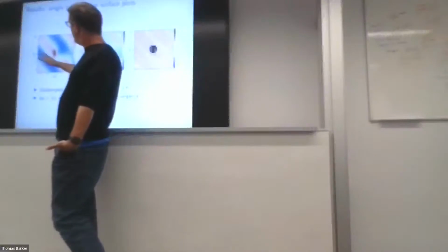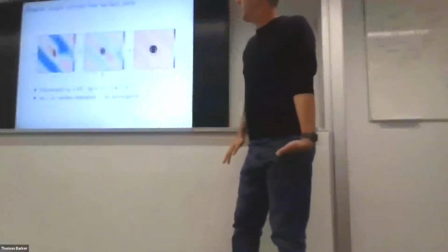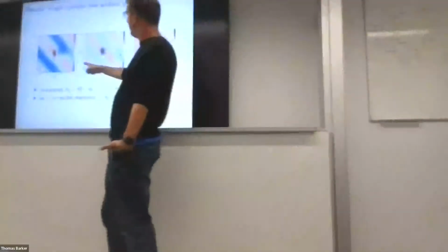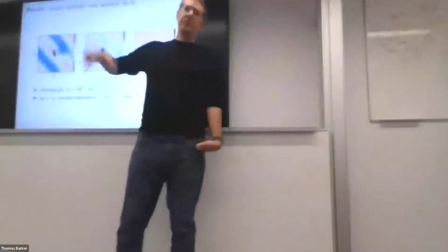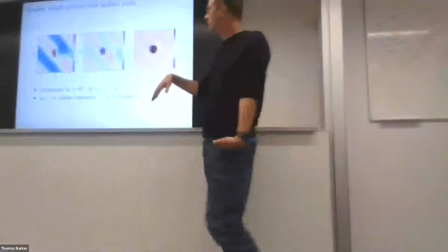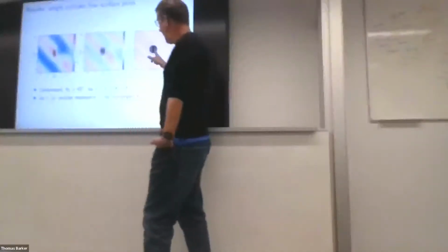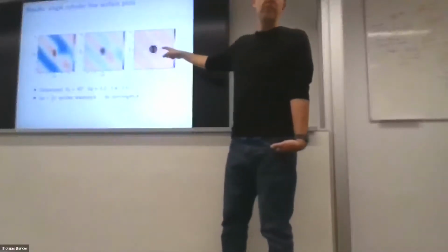I've got waves coming in, now long waves coming in from the left-hand corner at 45 degrees, and they're now interacting with this plate array cylinder. And what you can see, as the frequency increases, is that you're promoting this resonance inside the cylinder. So the surface is pumping up and down quite hard. And it gets worse, or more violent. And eventually, actually, this is quite serious, because the whole solution now fails to converge.